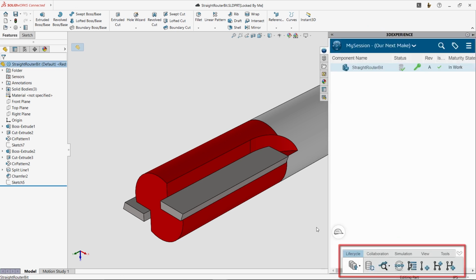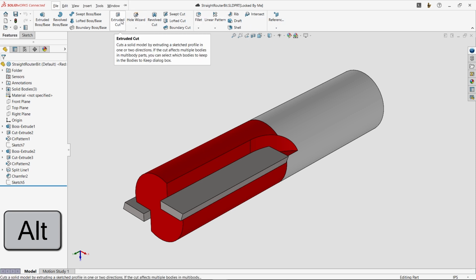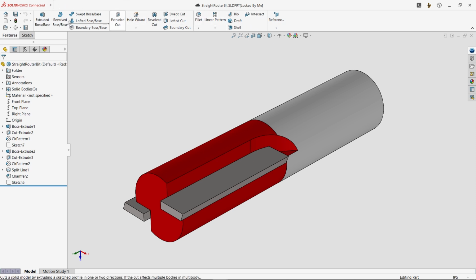Now that the Command Manager tabs have been simplified, let's focus on the individual commands. With the absolute beginner still in mind, I'll remove the commands I think are least likely to be used. I'll just hold down the Alt key on the keyboard and drag the commands off of the tab. You can also use this technique to move commands around the tabs.